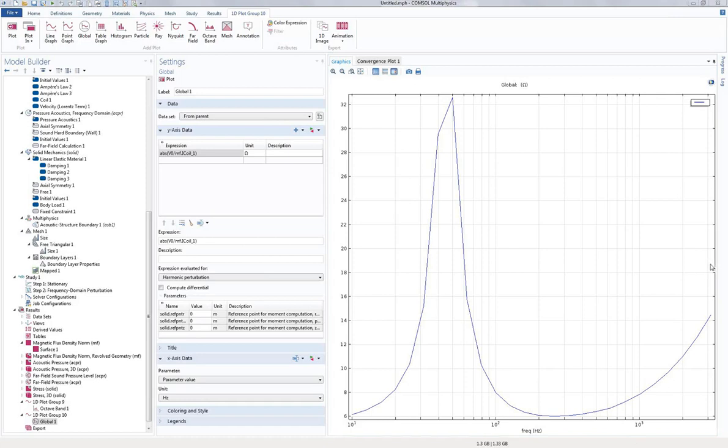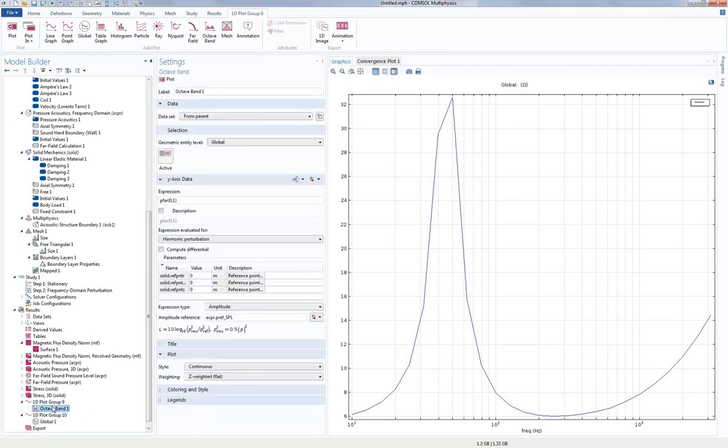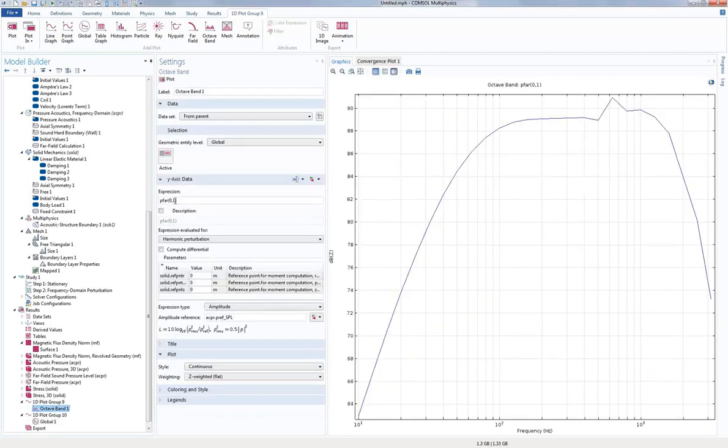simulation. So one question is, how can I get a sound pressure level from 2 meters away, actually, as this model only has a 1 meter radius space? Well, this model, in fact, only has a 15 centimeters radius space, and I already plotted it at 1 meter. That's the beauty of the far field pressure plot. I could go back to this plot and just set this to 2 instead, and that gives us a plot at a 2 meter distance. Looks kind of similar, not exactly the same, but with lower values.